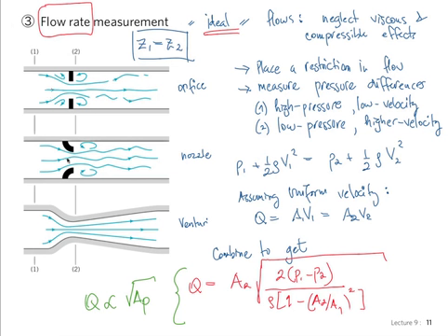As we look down through this catalog of devices, we have the greater losses in the orifice plates and the smaller losses in the Venturi. But the Venturi one is more difficult to construct and so on, so it will be more expensive. In an application in engineering, you will have to weigh all those decisions, to see if those little losses are acceptable for a lower investment price or not.